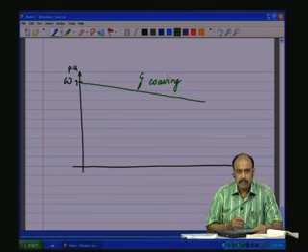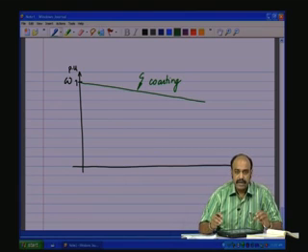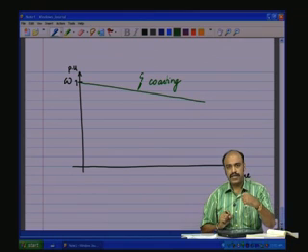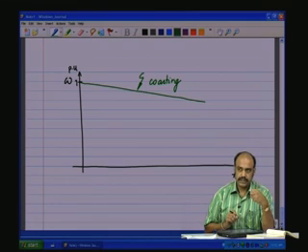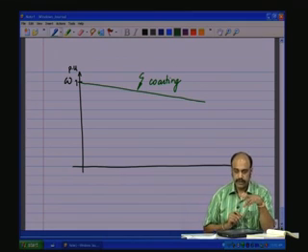Mechanical braking and dynamic braking are similar, only that in mechanical braking you are applying a mechanical brake by applying friction onto the shaft by means of brake shoes. That is, you are creating a mechanical friction where the energy is lost as heat due to the friction.